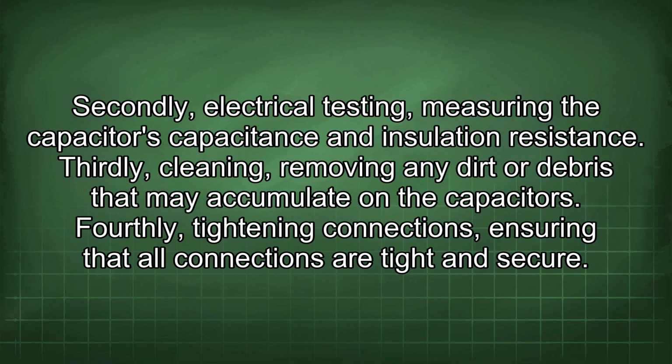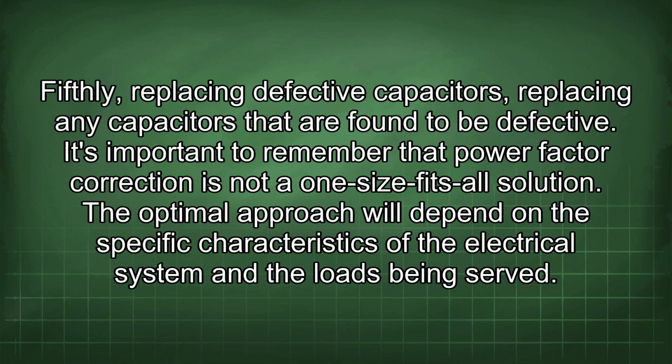Fourthly, tightening connections, ensuring that all connections are tight and secure. Fifthly, replacing defective capacitors, replacing any capacitors that are found to be defective. It's important to remember that power factor correction is not a one-size-fits-all solution. The optimal approach will depend on the specific characteristics of the electrical system and the loads being served.